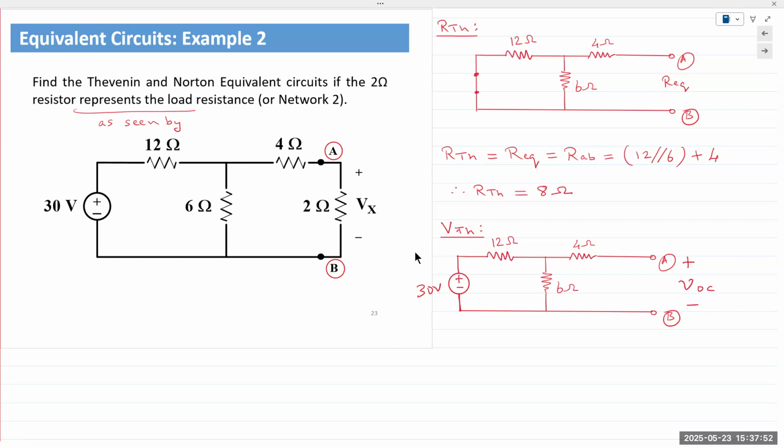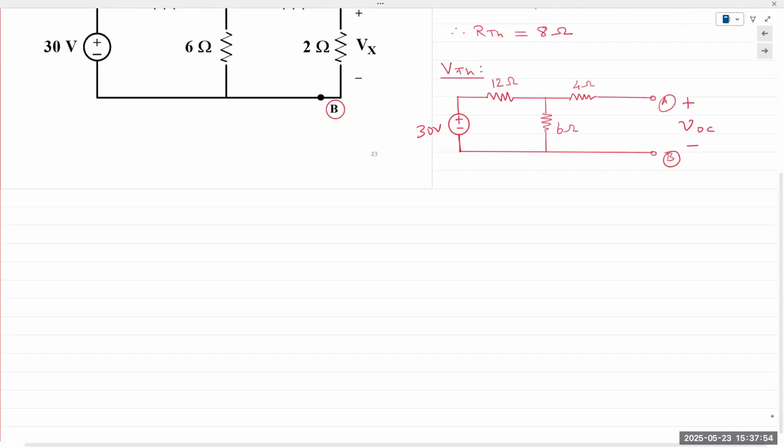Okay, what do you think the circuit is? Well, I'll tell you, the circuit is a voltage divider. But now you think on it and tell me whether you understand it's a voltage divider. Again, the same concept, right? We have current coming from the source going in this direction through the 12 ohm resistor. When it reaches this intersection right here at the top, some of it would go down the 6 ohm resistor, some of it will go to the 4 ohm resistor.